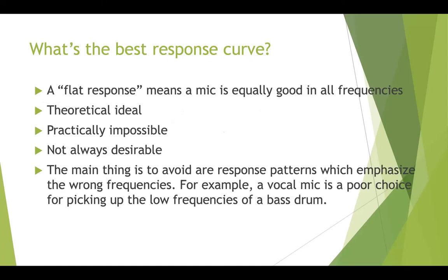The main thing, as this slide says, is avoid response patterns that emphasize the wrong frequency. So don't use a microphone with a vocal emphasis on a bass drum. Don't use a microphone with a bass emphasis on a voice. It's going to make the person sound muddy, and they're not going to sound natural.